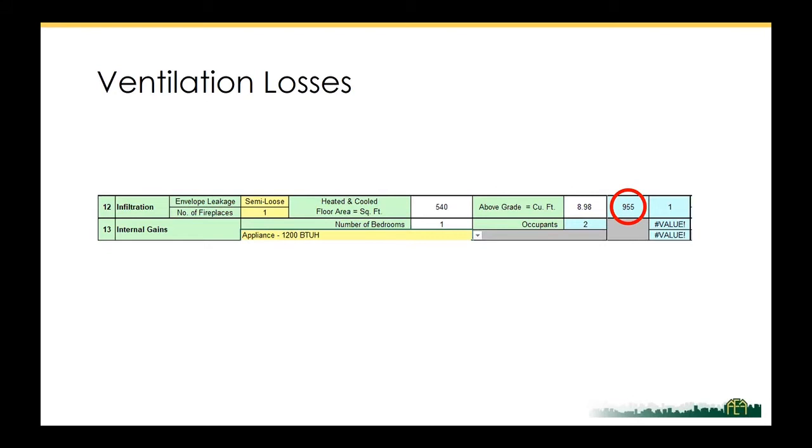Well, before I dig into the question, within the appliance, 1200 BTUs per hour, I can imagine incandescent lights versus LED lights, or better refrigerators, all these variables. I'm wondering how much of a difference does it make? Is it really worth digging into that with 1200 here versus the other values being brought to bear, like the energy of the compressor? Well, actually, at the end, we're going to look at the values of all three for internal gains. And it actually makes quite a big difference when you're doing a small unit like this.